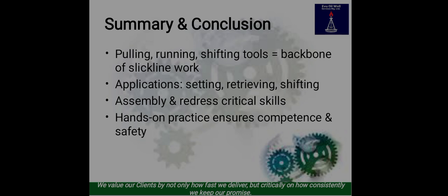What were the findings? Upon recovery, the bead shifting tool's keys were bent. The shear pin had failed prematurely, and the fishing neck was deformed. A post-job review revealed that a C-type sleeve had been installed, so at this point, a B-type shifting tool was mistakenly used.